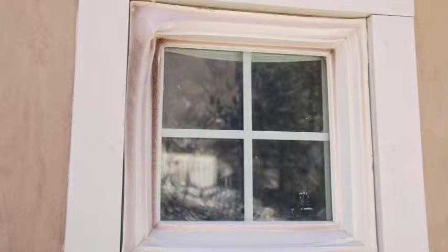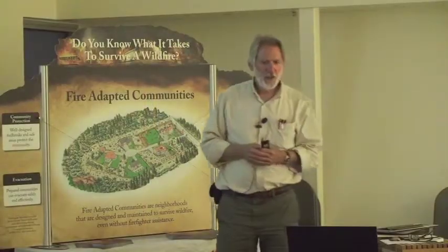Certain windows, and this is a vinyl window again, would have a propensity to sag with a radiant exposure, even though the glass won't break. So this would probably require replacement, and I'm sure the insurance company would replace this window. So from a no damage perspective, you can expect this kind depending on the radiant exposure that particular side of the house sees. Okay, we're good.